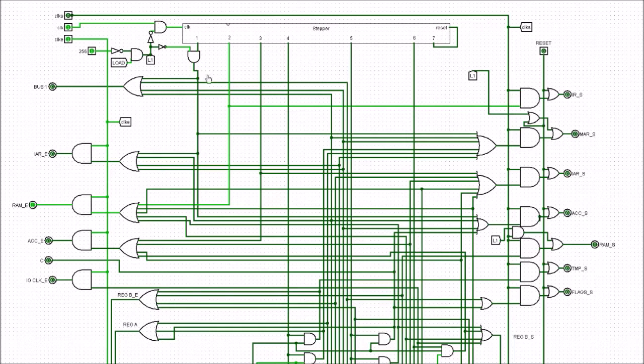So we have to have this value 256 coming from the counter as well, back in here and get through the AND gate. And you can see here the place where we had the memory address register, it can be picked up from this point L1. Also the point down here for the RAM set can be picked up from point L1. So we don't need to bother doing these, they are taken care of automatically.